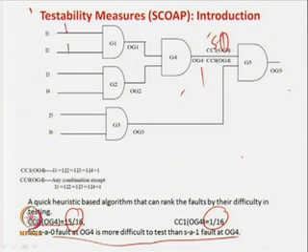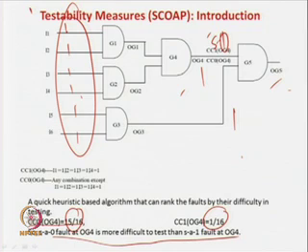Okay, so the answer is 1 1 1 1. And for this one also has to be 1 value to be propagated. So, you have to 1 1. So, we have generated the test pattern by sensitize, propagate and justify approach indirectly.